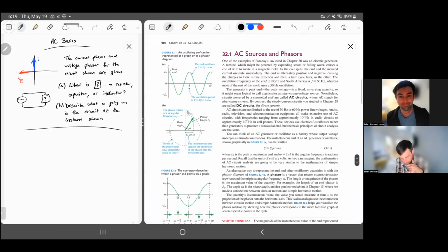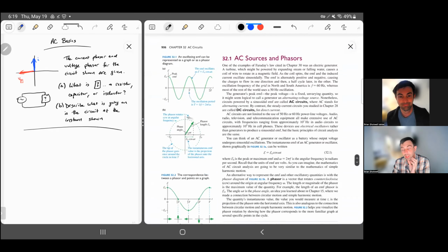All right, so a phasor is a mathematical representation of a sinusoidal function. So really what we're talking about here is voltages and currents. For every one of these circuit elements, the voltage and the current is going to be a sinusoidal function of time. So it has a graph that looks like this when you plot it versus t. But there's a different way of representing it that will be handy for us.